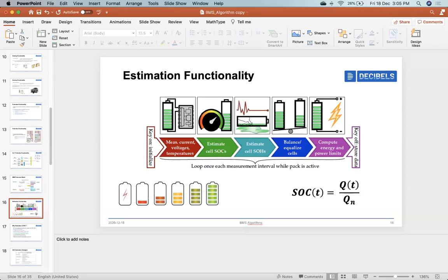For the other question, eco mode and sport mode in EVs are restricted by discharge currents only. Yes, you could limit the requirements at the motor. Once you limit your requirements at the motor, at the controller level it doesn't even pull the higher currents from the battery pack.